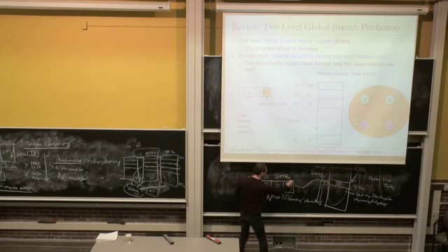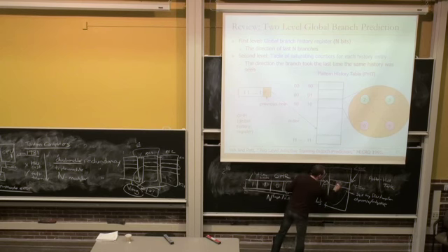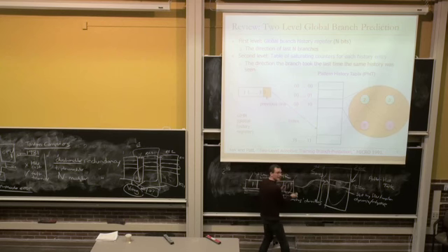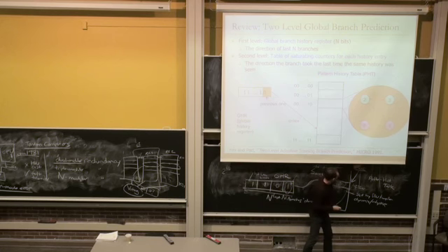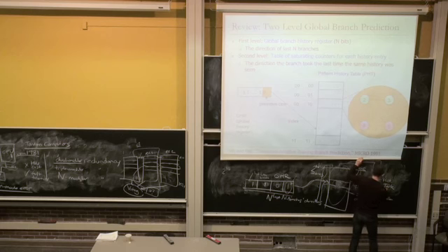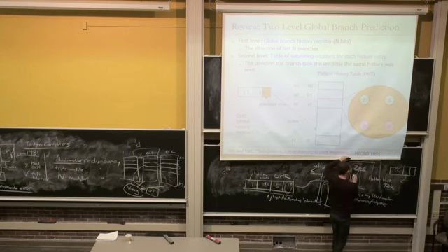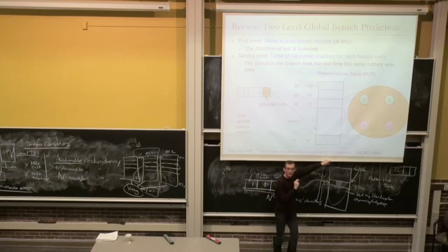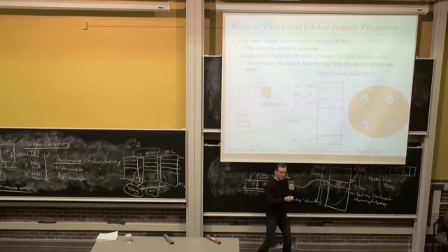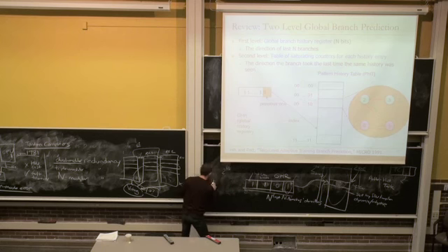And if you have a single history, if you have a single pattern history table counter for a given history, then you cannot distinguish between that. And what Pentium Pro did was, it had 4 different tables, and based on the lower 2 bits of the program counter, you would pick which one to use, so that you can eliminate the interference between different branches.